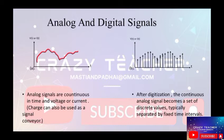But when you do a digitization, at every point we basically do a sampling. At regular intervals of time, we sample the signal, and what we get is a set of signal samples separated by time intervals. After digitization, this continuous analog signal becomes a set of discrete values only. They are typically separated by fixed time intervals, which is known as the sampling interval. After each sampling interval, the value is sampled again, and these values are stored.